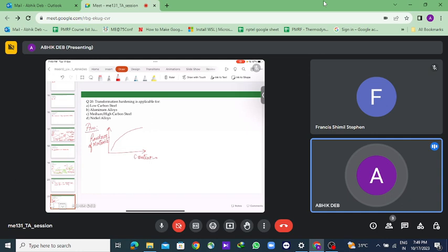You see what happens in the carburizing process is, in order to make some carbon distributed from the bulk, I mean, reduce some of the hardness. Carburizing, nitriding, all of these are surface processes. Why will we require to distribute it in bulk? That is not the correct answer.